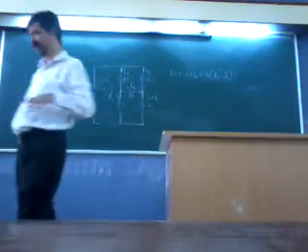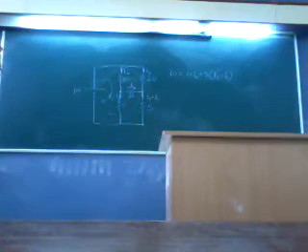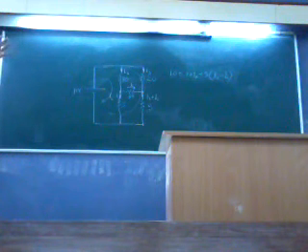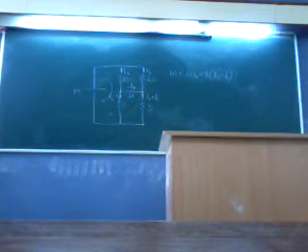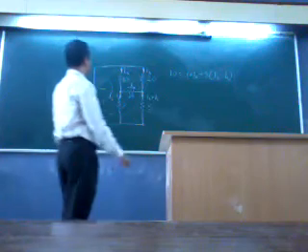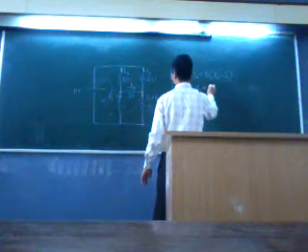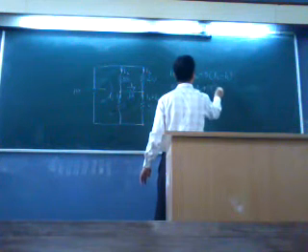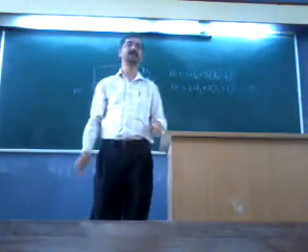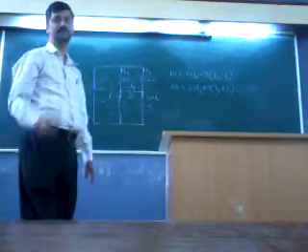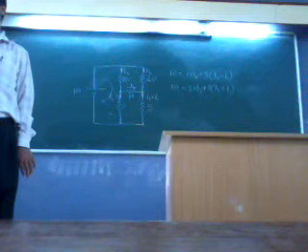I will not go on simplifying the equations. Solution of 1 or 2 or 3 or more simultaneous equations is a high school level task. So we will just write the equations, leave rest of the things to you. Then second would be again 10 is equal to 20 I3 plus 5 into bracket I3 plus I1. Because our logic is voltage, battery voltage equal to voltage drop.